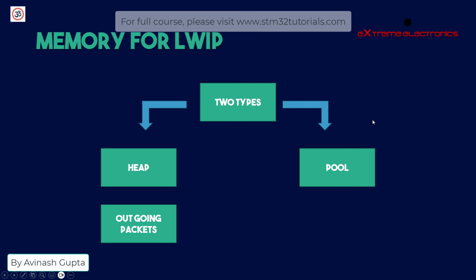While on the other hand, when we have an interrupt from our Ethernet controller, any Ethernet controller, whether it is internal or external to the microcontroller, we generate an ISR or interrupt service routine that a new packet is received by our Ethernet controller, and in that case LWIP uses a pool to allocate memory for the incoming packets like this. The pool memory is fast and deterministic, but it has a disadvantage.